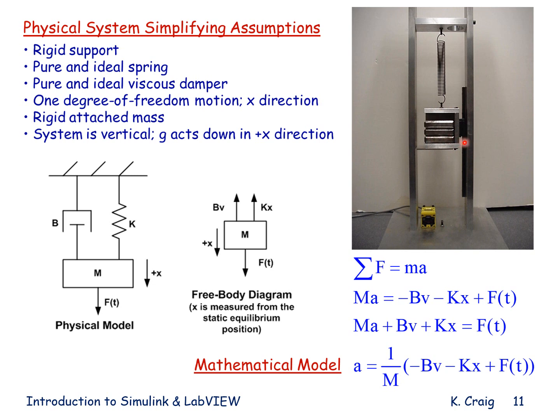Because the linear bearing restricts the motion of the mass, confines it to simple up and down motion, prevents it from moving side to side, in and out, or twisting, I have essentially a 1 degree of freedom system, and it's in the x direction. Degree of freedom means how many coordinates, independent coordinates, are needed to completely describe the motion of the system at any time. In this case, I only need one, and I'll call that x, and I'll call positive down.